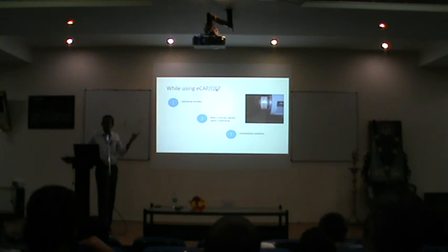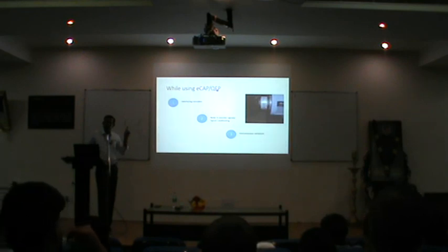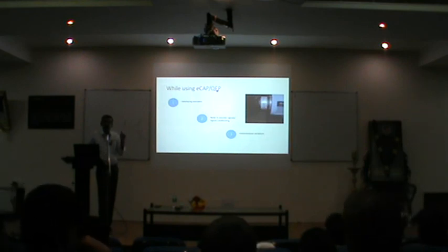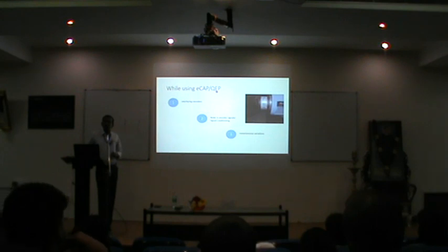the QEP pin or eCAP pin. You have both of them in your C2000 microcontrollers. When you look at these pins, the data sheet says a voltage of not more than 3.3 volts should be fed to it. You have a mismatch, so obviously you have to look for signal conditioning. And when you use the signal conditioning, make sure the signals are not distorted.